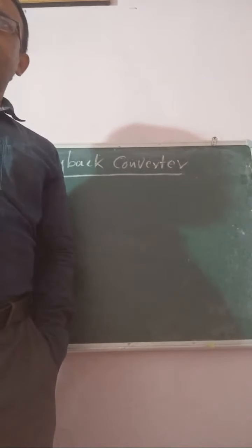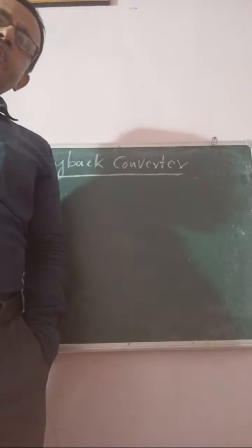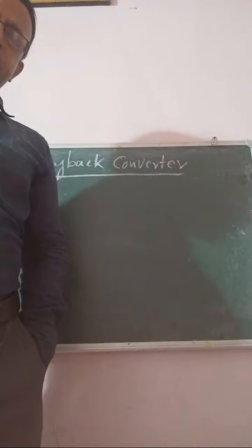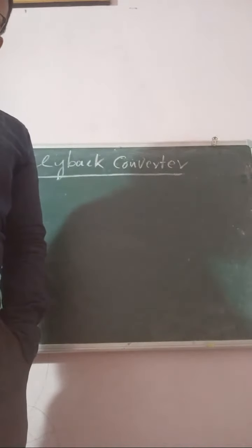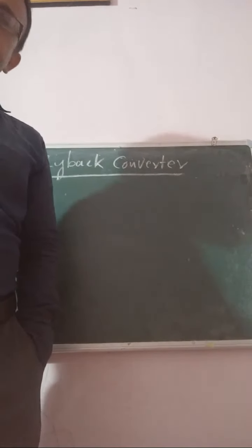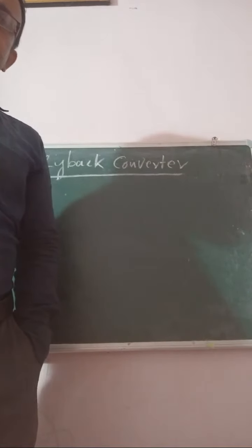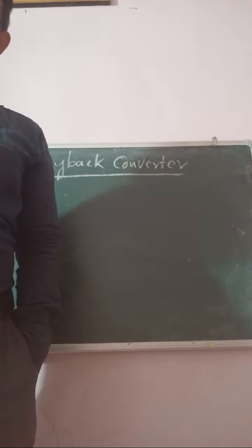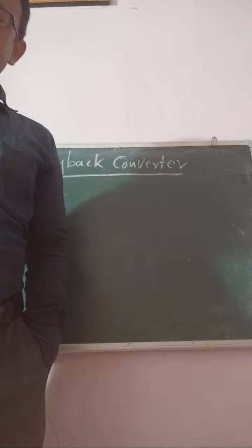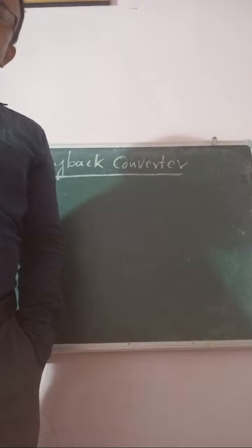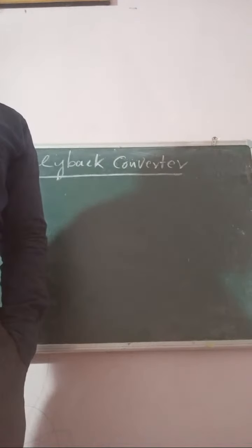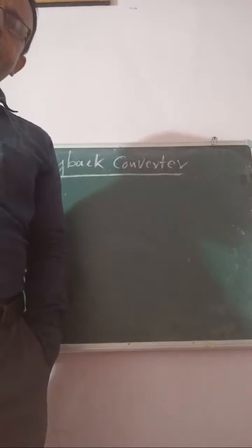A ferrite core transformer is used for high frequency application. Here we take a high frequency transformer to increase the power density, because the flyback converter is generally used for low and medium power supply in industry.